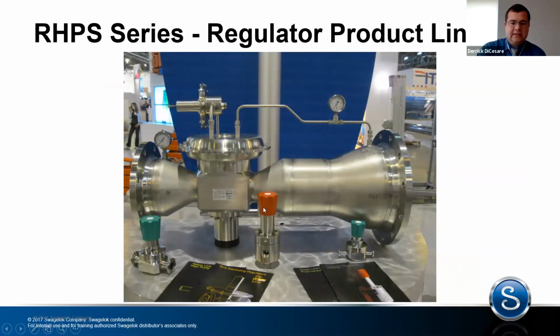To get an idea of size, this is a 3/4 inch pressure regulator. This is a 4-inch dome loaded with a pilot with an external feedback line with giant flanges welded on the end. Just to get an idea of some of the scope and flexibility that we have to modify a regulator for an application. This would be done at corporate, but we do have a way of creating this style of solution.